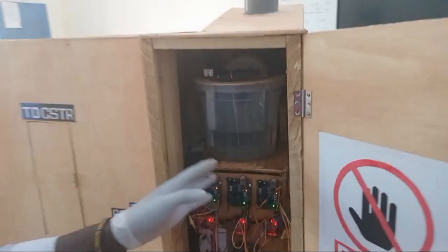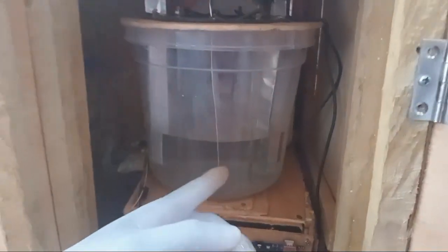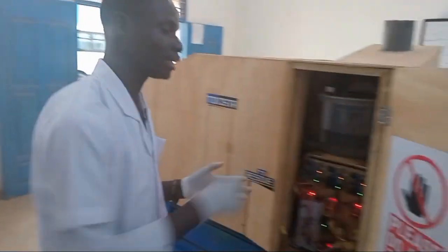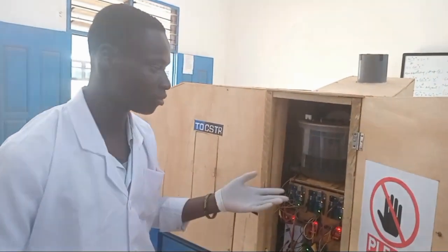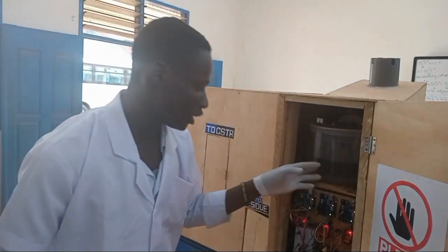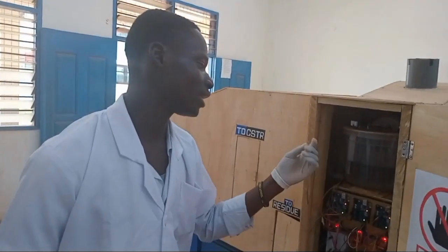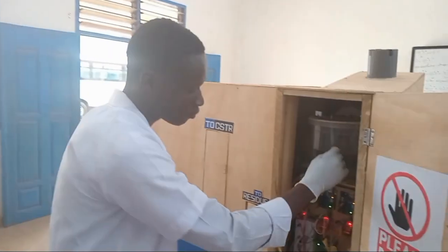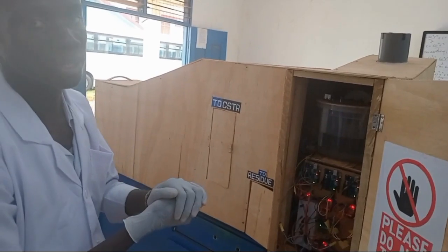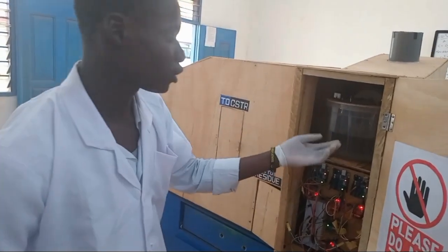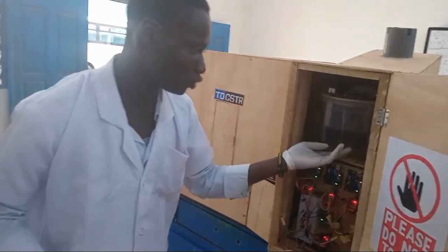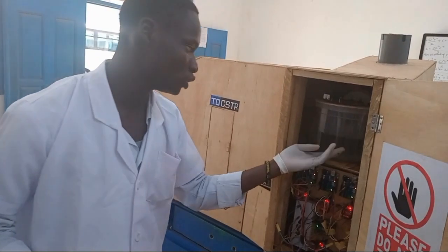So the function of the anode is to supply metal ions into the water, and the function of the cathode is to supply electrons from the cathode to the anode, which will destabilize surface charges on suspended solids, emulsified oils, heavy metals, and many more. And flocs will be formed by hydroxide ions, which will form heavy or compact particles, which will then be lifted up by the hydrogen, which will be produced on the cathode.